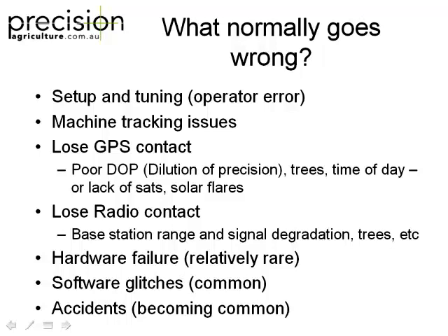And you need to know whether you've lost GPS or whether you've lost radio. Remember back to my original drawing, if you don't have the base station connection, that's going to be a completely different range of reasons why it's not working. Sometimes you get hardware, but mostly software. They come and do a software upgrade and it creates all these new problems. A bit like when you get your Windows upgrade, all of a sudden you've got problems, haven't you?